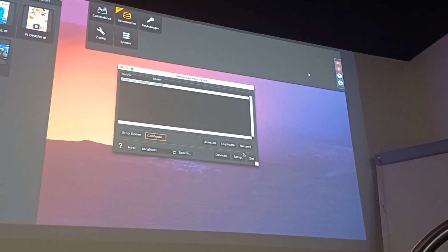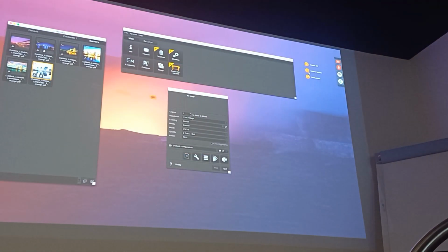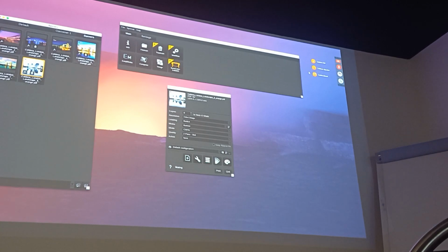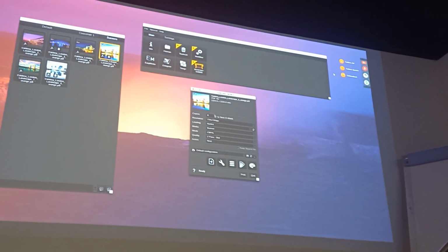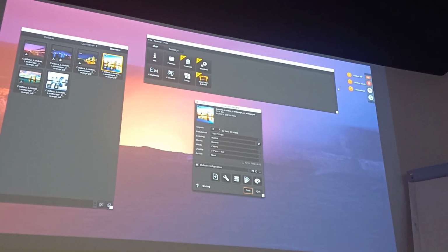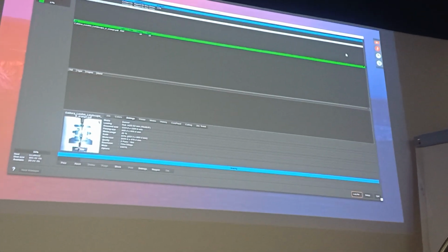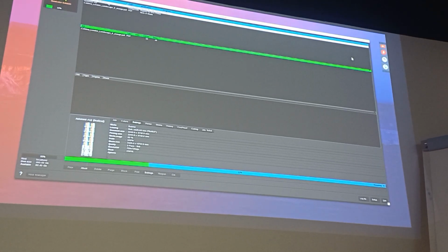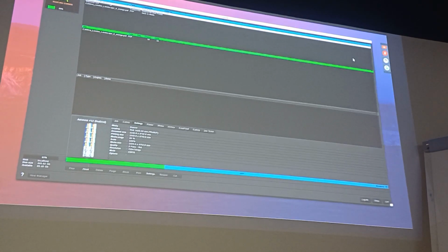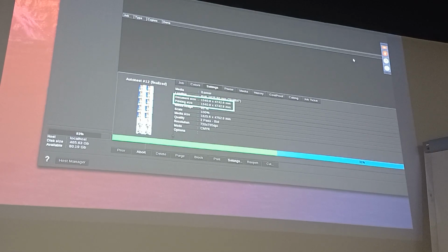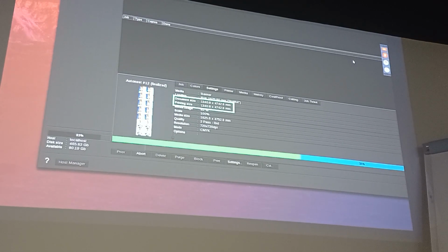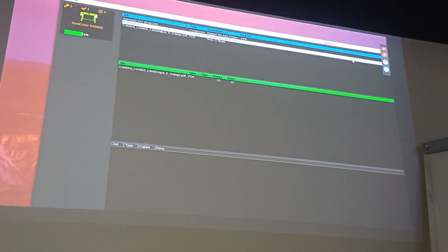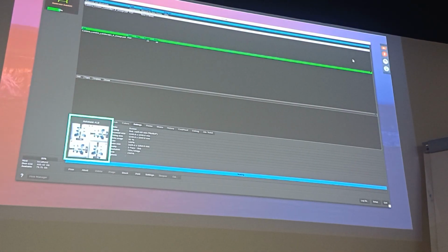Let's check if everything works as expected. I'm going to nest a bunch of images, then I will check what we get in the spooler. Here, we can see that an AutoNest job is already ripping because its size is very close to 5 meters long, which is the limit we set up earlier from the Nestomatic print conditions. And next images that didn't fit in this AutoNest are nested in another AutoNest, etc.